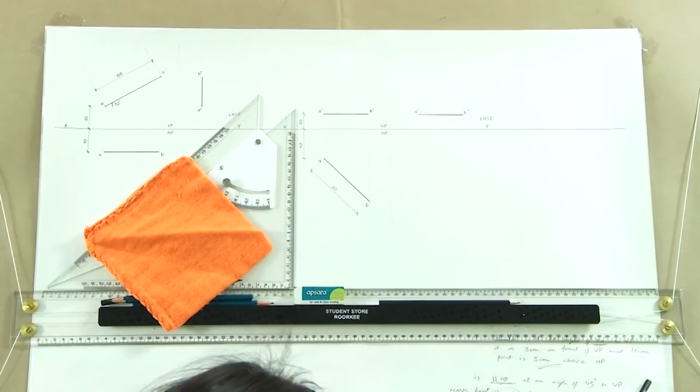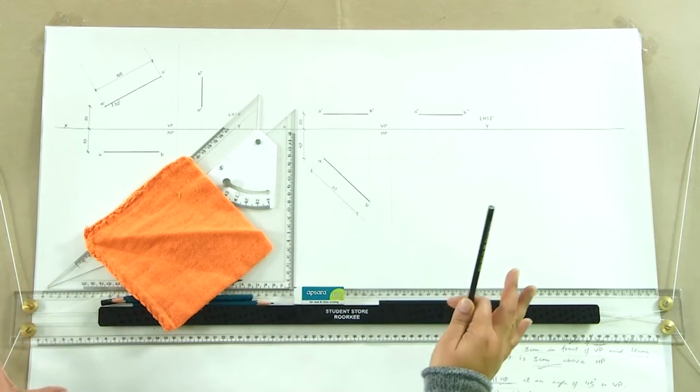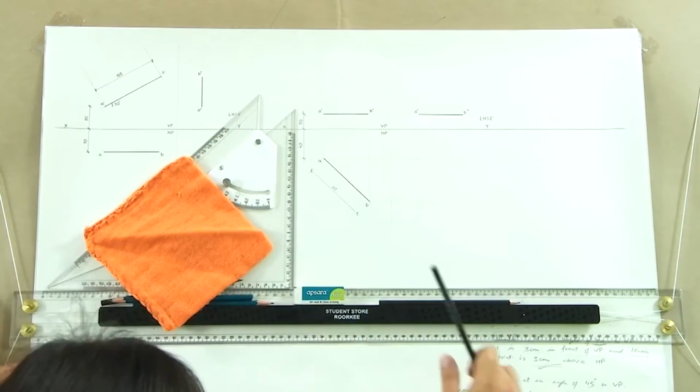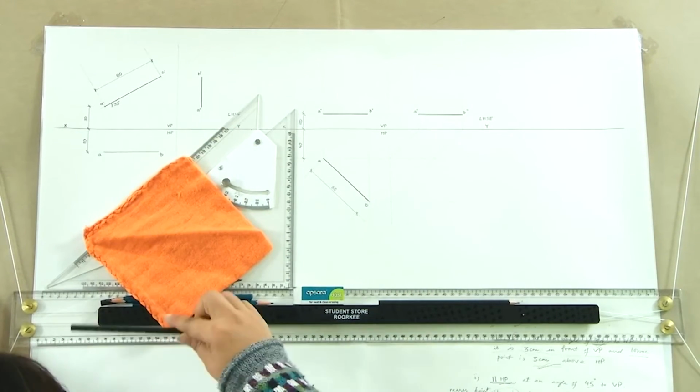To come up to this level where we can directly darken it, you have to have a lot of practice, and after practice, of course, it will be much faster, but until then draw it all in light and then gradually darken it. And the last thing that should be darkened on your sheet is the border. I am not making the borders here, but if you are to make the complete sheet for say submission in your class, you need to make a border, write everything, which should be the last thing that you should be doing. Darkening of the border, light border you could do, dark borders you should do later.